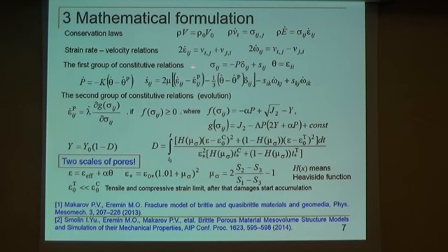These are strain rate velocity relations, and the most important part of the mathematical formulation is constitutive relations. Here we describe the elastic behavior by using a hypoelastic formulation, the relation between stresses, stress rates and strain rates.